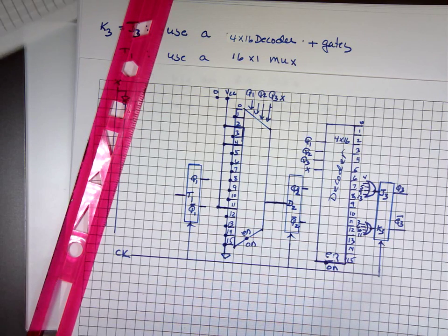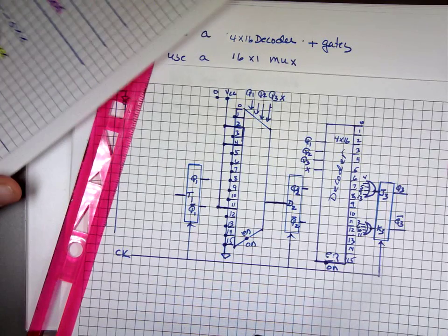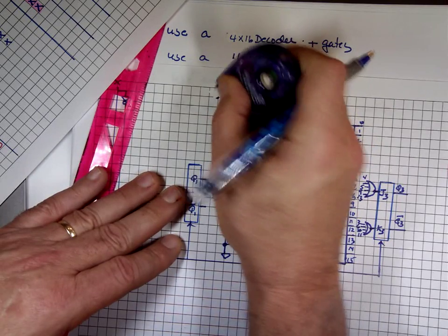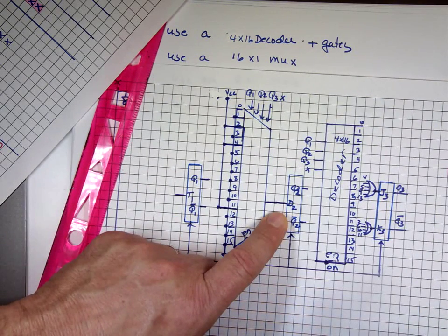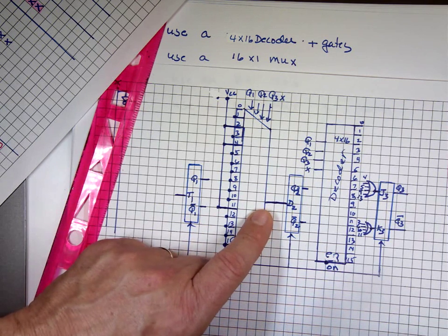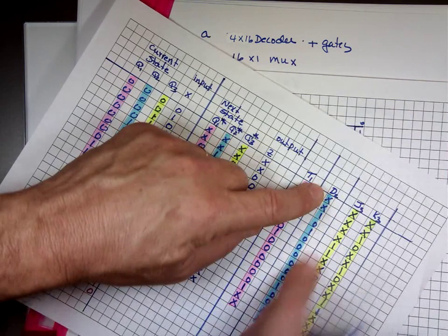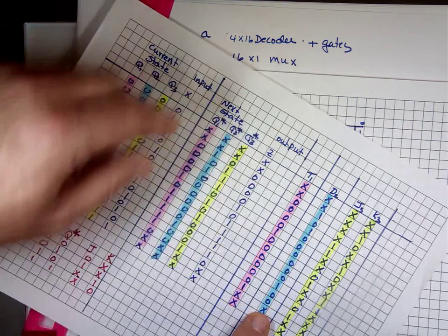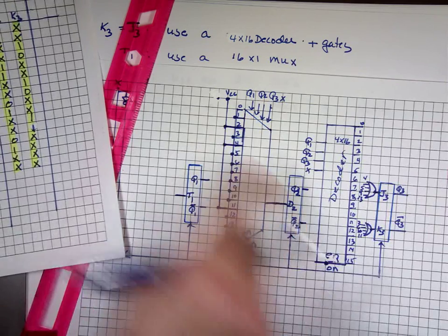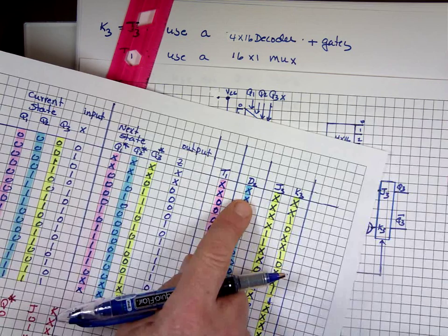Did you know it's connected to D? Huh? Did you know it's connected to D? This is connected to the D input, yes. The output. Is that what you're asking? I don't understand why. Well, you have one output, right? So you want D here to have these values. So when you put 0, 0, 0, yep. When I'm putting 0, 0, 0, D is going to have whatever attached to 0. In this case, I decided to make that a 0 just to make my life easy. I could have made it 1 or 0, don't care. I decided to go with zeros.